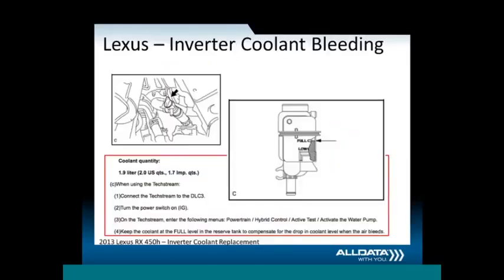Here's another example I ran across. We were working on a Lexus recently, and a lot of people think, kind of old school, that you can just use the bleeder valve and open up, turn your heater on, and bleed the coolant system. Well, recently I was in a class with some Toyota and Lexus executives, and they explained how important it was to use a scan tool to actually initialize a check valve within the coolant system when you go to bleed the coolant system.